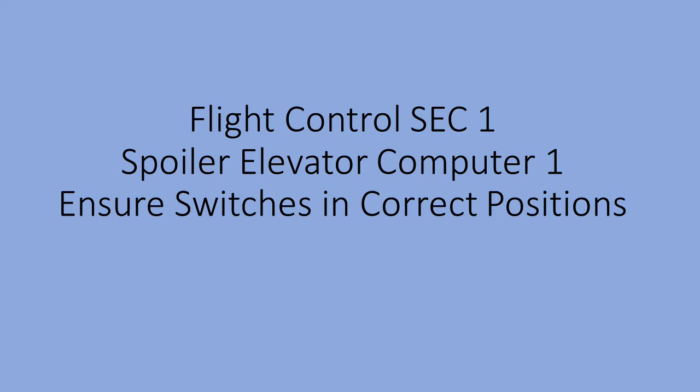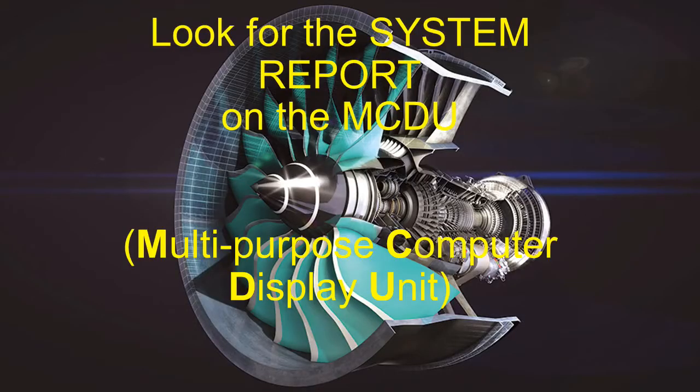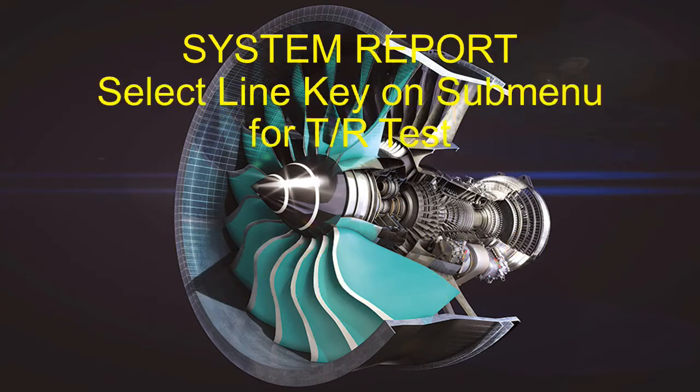All right, and what you're going to do is look for the system report on the MCDU. MCDU is your maintenance panel, or your maintenance page. Here you're going to look for system report test eng for your engine, and then you're going to push the line key that's next to the FADEC indication, because you're trying to get the main menu for the engines.